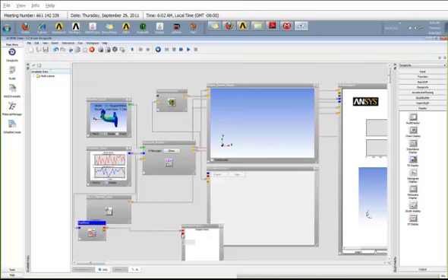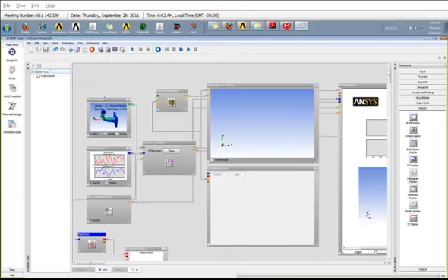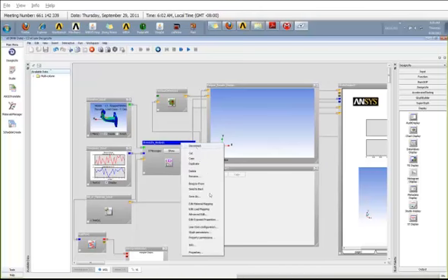Let me move these things a little away here. Okay, so I have my simulation input ready, time series input ready. Now let's go into the stress life analysis and set all the other parameters. I'm going to go one by one. The first one that I'm going to do is edit material mapping. I want to see what material I'm using for it.